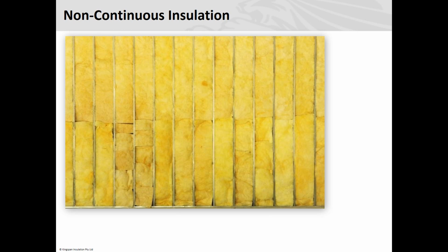Could you put cladding on the outside? Well, you wouldn't put it straight on that, but if you had a shipping container, probably the best way to go would be to maybe batten it over, say 600, insulate in between it, and then put an iron cladding on it. That would be the way to go. So your shipping container basically becomes your studs. Yeah. But if you were to screw some type of fixing, you wouldn't want to be putting exterior cladding onto that and then gluing it to the shipping container. We wouldn't really say that would be a great construction way of doing it. You want to have something solid to fix it to.